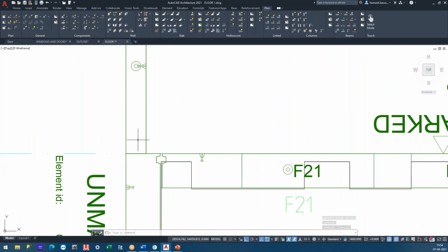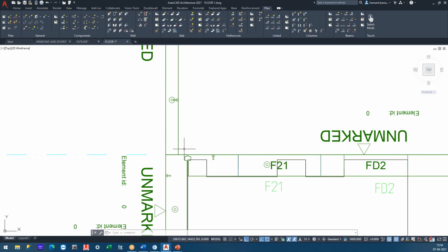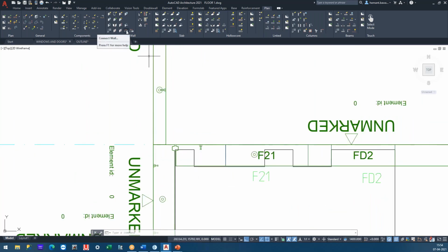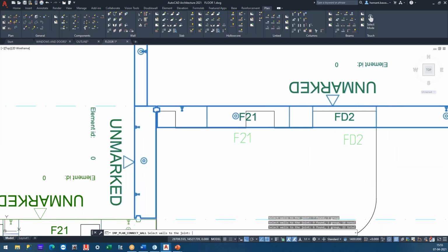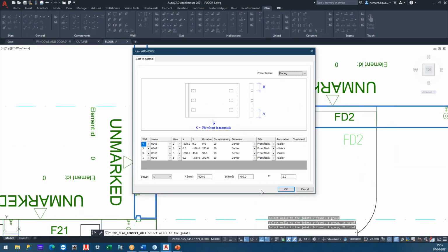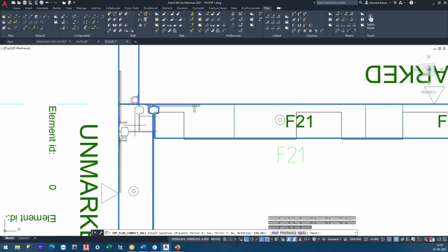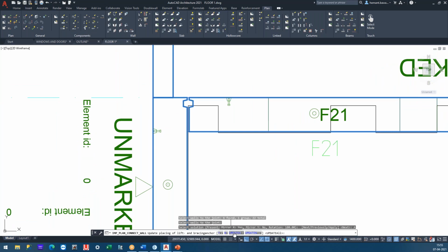Now this connection won't do because we would like to connect these walls to these sandwich walls, and simply adding them here won't do. So we have another command here for connect walls. Here I will select these three walls. Okay, and as you can see, it has given me a rough outline of how the walls will be connected, and I think I'm okay with it. So I will apply, and of course I will update all the lifts and the bracing anchors.